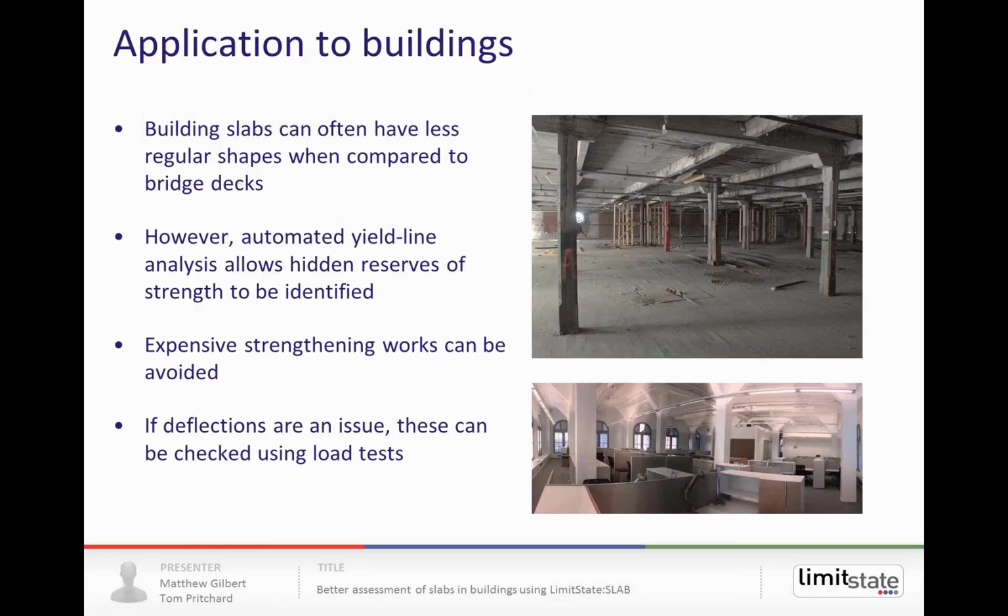And in the case of an existing building, serviceability might be an issue, but if it is, then we can often actually do physical load tests. We can actually bring in containers carrying water, pump the water up, and actually exert load and measure the deflections.